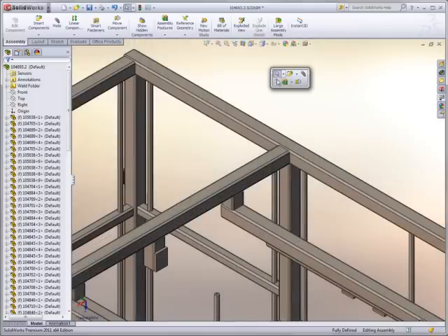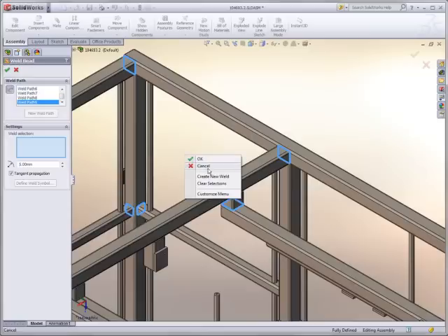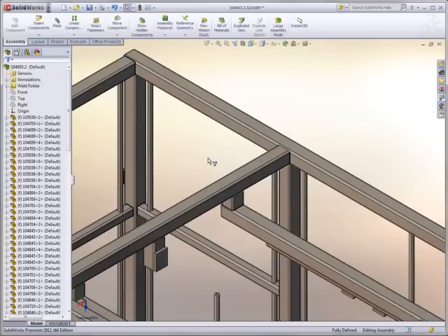When working with complex welded frames, you might need to create a significant number of welds. To tackle these cases, the weld bead tool has one last powerful capability: the new Smart Weld Selection tool. Once enabled, all you have to do is swipe your cursor across the parts to be welded together. The selection tool automatically finds the appropriate choice and creates multiple welds at once. It's extremely fast and easy.